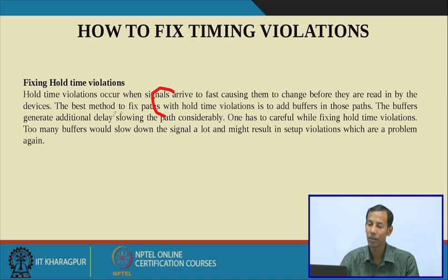So the best method to fix the hold time violation is to add buffers on those paths. That means you can add buffers on the particular clock path, so that the clock will arrive a little bit later, as the data has already arrived.